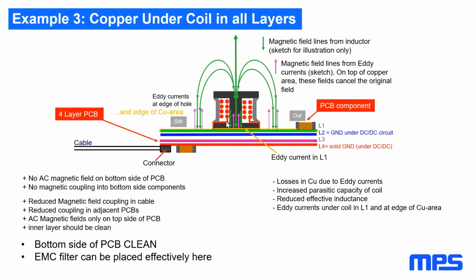So with an inductor that has more than one layer of windings, the outer winding that should be connected to the steady potential VOUT is shielding actually the high dV/dt from the switch node. You can also think the other way around.